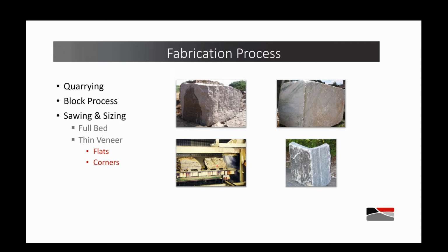It damaged the integrity of the stone, which would cause problems further down the fabrication process. And so they came up with multiple gentler ways to extract the rock. You'll be able to see in that picture on the top left-hand corner, the core marks down the side of that rock. That piece of rock was extracted using a kind of modern-day alternative to what they used to call plug and feather, when they drill a small hole and tap a tapered plug into it and push feathers down the side of it to expand and cause a crack in the stone.